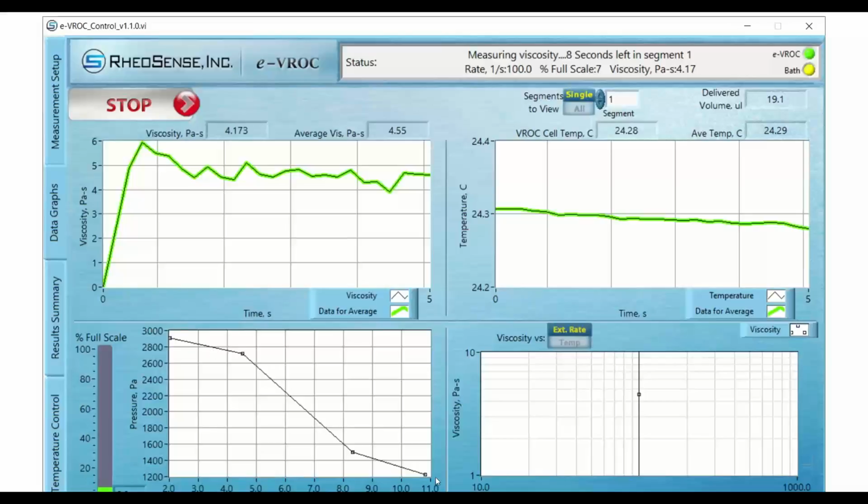And then on the bottom left here, we have, as I said, the pressure profile. And this, as we said, looks different than for our uniform channel, because now we don't have something that's linear. And one of the signs that we have a good experiment when we're dealing with the uniform channel is that we have an R² value that's close to or equal to 1. But now we can't use an R² value here because it will never be 1.